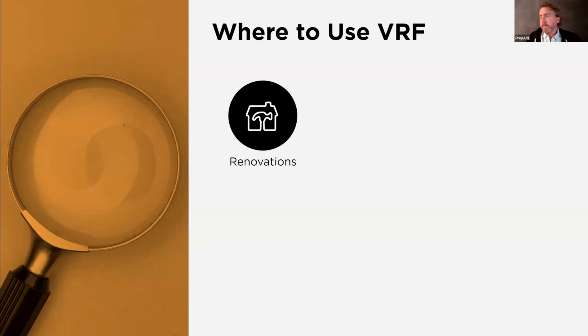So there's not a lot of variability in needing to choose these systems in practice, because usually if you have a project type or a specialty, you're going to know what it is. So if you frequently do renovations, you're probably looking at VRFs almost all the time. So that's kind of critical. I worked at a firm that just did schools K through 12 and higher ed. So we were pretty much doing package units and VAV the whole time.